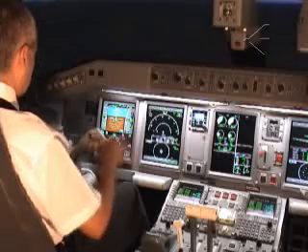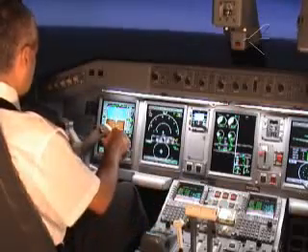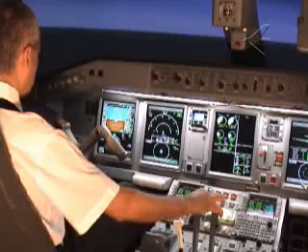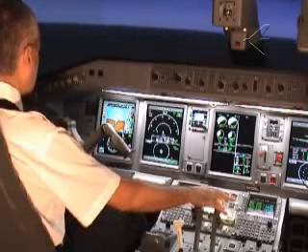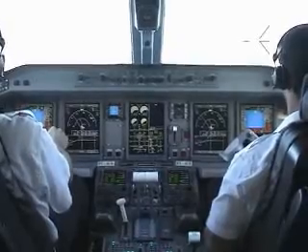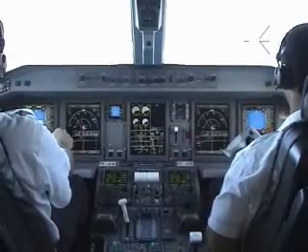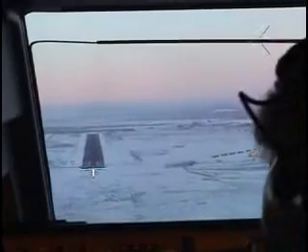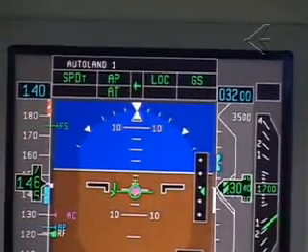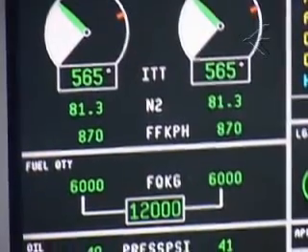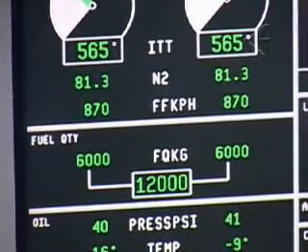While performing an Autoland operation, guard controls from approach to touchdown and be prepared to take over manually if required. Anticipated and appropriate pilot intervention will be necessary in any case preventing the aircraft from safely landing in the touchdown zone. When an Autoland is planned, additional preparation is required. Considerations like crew qualification, destination airport meeting CAT 3 requirements, equipment required, fuel and weather must be taken into account before dispatching the aircraft.